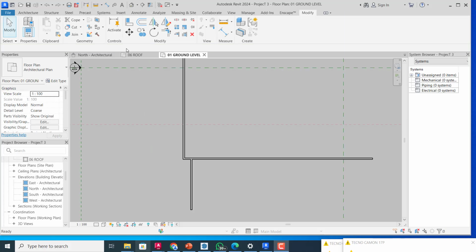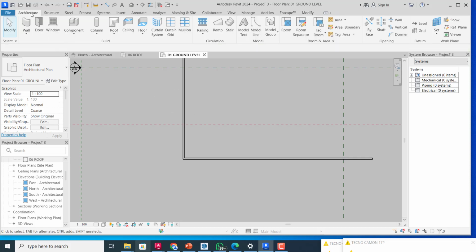The first tool we are going to talk about is the align tool. We can simply align a wall. For example, I drew a wall here and probably this is a mistake, and I want it to come straight this way instead of the way it is at the moment. I can just simply use the align tool. So let me delete this wall. I can just select it and click delete and it will go.